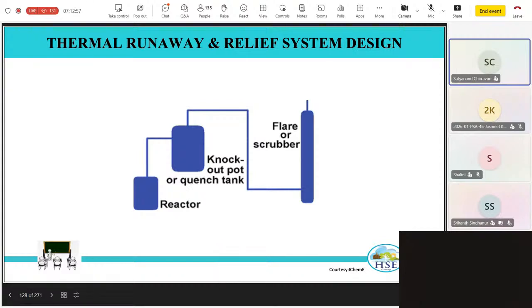We talked about screening of process. First we have a process, or you're carrying out a process, or you're managing a process. First of all, you look into the chemistry and figure out what exactly you have. You try to understand the higher hazard groups. Then look at oxygen balances and see if oxygen from within the molecules is going to be dangerous or not.